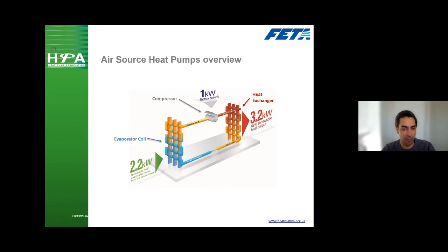I mean, Craig is working for Vaillant there, and I'm sure you'll thoroughly agree to this, that to get a gas boiler to condense, we need to be at that lower end of the spectrum of temperatures to get the best out of a condensing gas boiler. And that's just the same with a heat pump. We want to get those temperatures as low as possible, and that does mean a design consideration in the design phase for the radiators in the system.